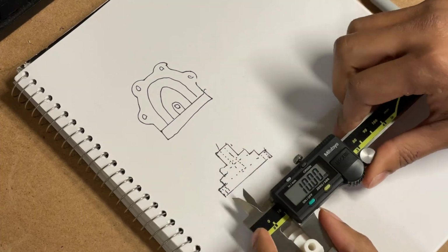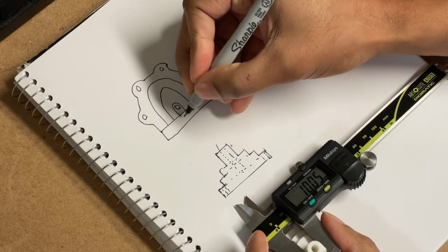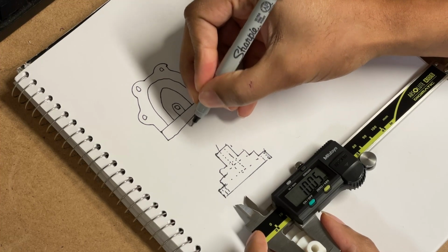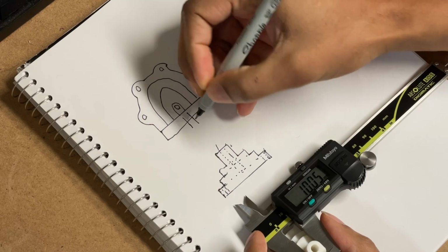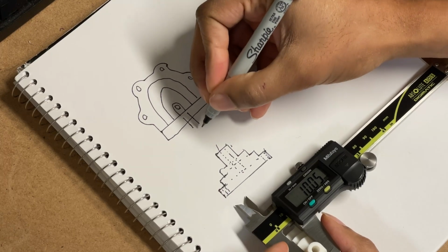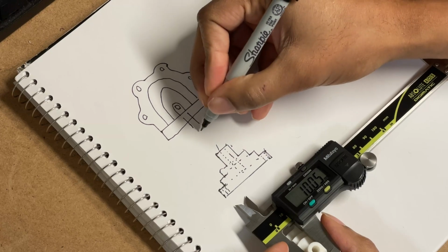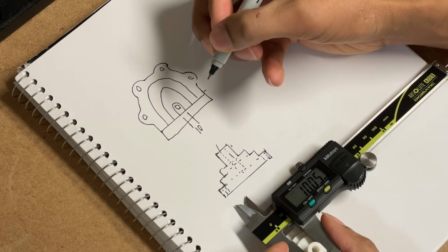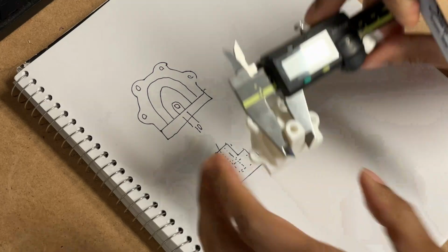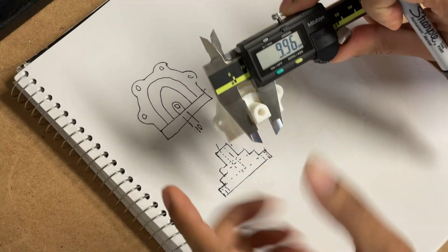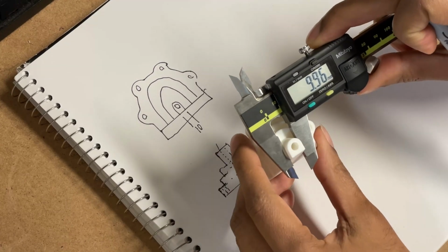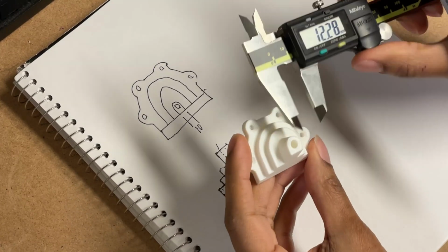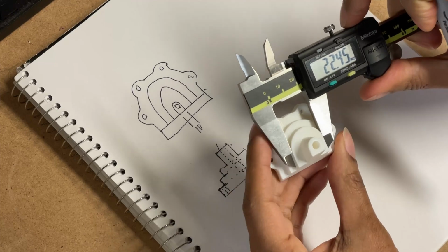Okay, so that's 9.5 over here on this diameter. Here's my extension line. This might get messy here in my drawing. But I'm not gonna write down 9.5. I'm just gonna call that 10. Because again, we're reverse engineering. We're not trying to replicate exactly this. We're trying to replicate what this is supposed to be. So in this 3D printing process, maybe there were some dimensional inaccuracies.